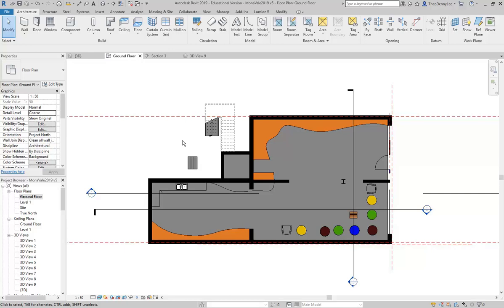Okay, so I'm at the stage now where I want to start to set up some preliminary renders of this space. And so to render, normally you need to have lights, particularly for the interior, even though you will have sunlight automatically in all of your Revit scenes because the sun is there whether you like it or not.